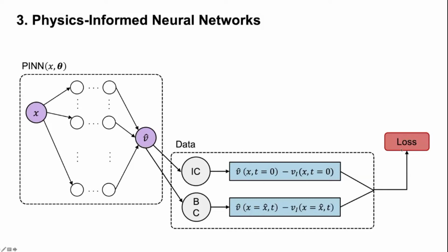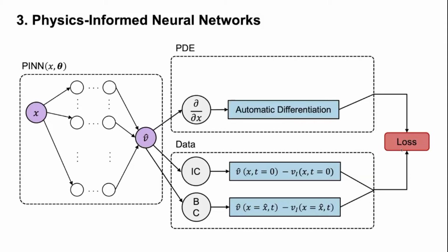Now I said we use also a numerical setting here. So we use the neural network as a PDE Ansatzfunction, as a global PDE Ansatzfunction. That means we can use this primary variable here, the output of the neural network. The output of the neural network is defined as the primary variable, and then we can differentiate this output of the network with respect to its input by means of automatic differentiation.